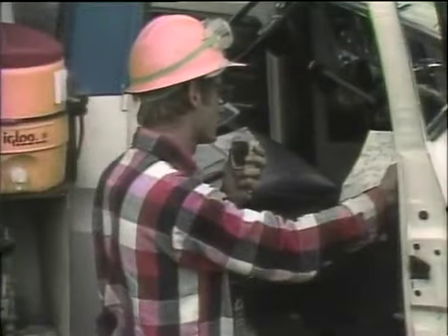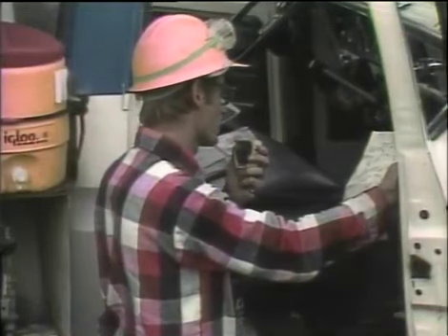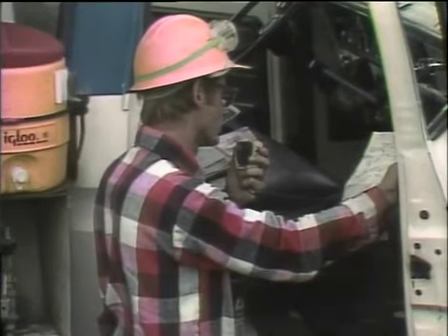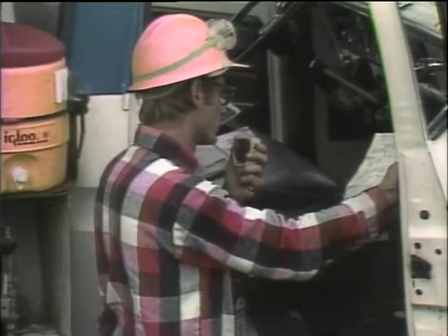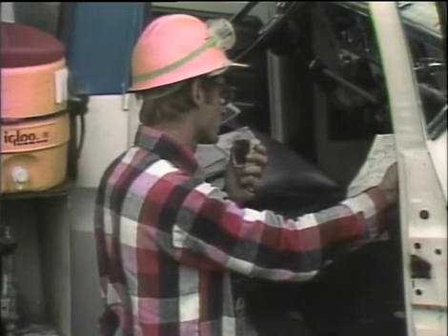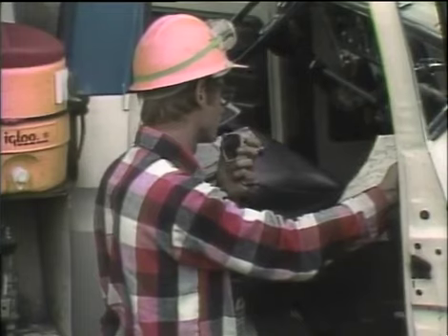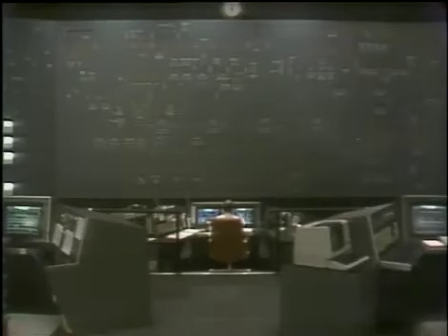The dispatcher is then informed that the job is completed, the grounds are removed, and the circuit can be re-energized. "We've completed our work, removed our grounds, tags, like to be reported clear." If all the work is completed on the circuit, the dispatcher can close the circuit and instruct personnel in the substation to remove the tags.